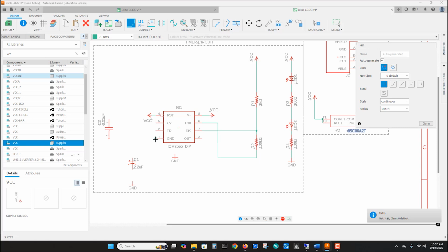Connect pin 1 of the 555 timer to C2 pin 1. Connect pin 2 of C2 to pin 5 of the 555 timer. So that goes back to pin 5. Connect C1 cathode to ground. C1 cathode goes to ground. You can see where too many wires would get very hard to follow. Lines that cross can be confusing.